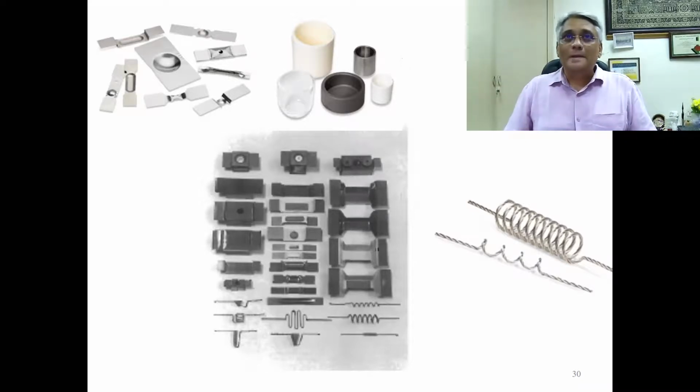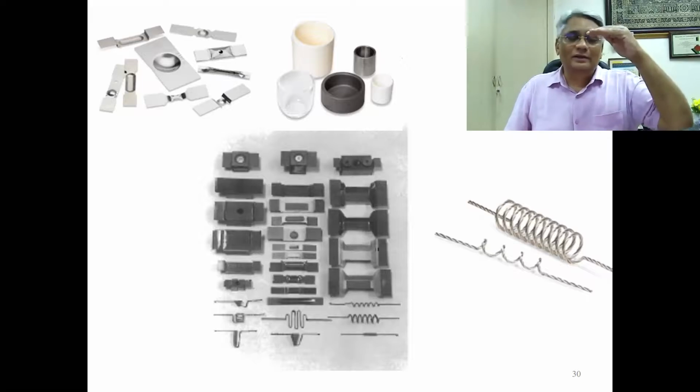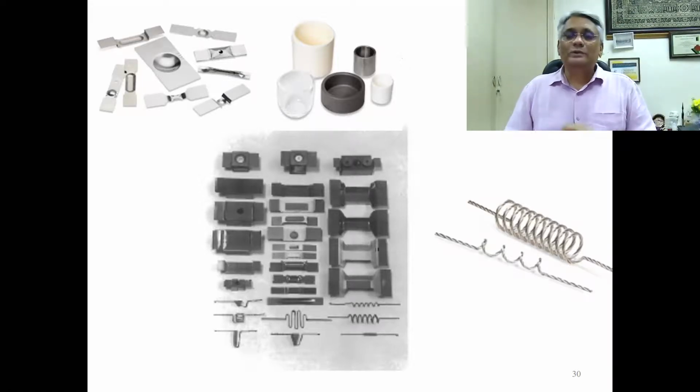So I want to make sure that when I'm depositing, if there is any impurity, when I get a layer of aluminum or niobium or some other low temperature superconducting materials, right? If there are some impurities coming from these crucibles, because after all you're heating them to their melting points, then the physical properties can change. So we don't want that to happen.